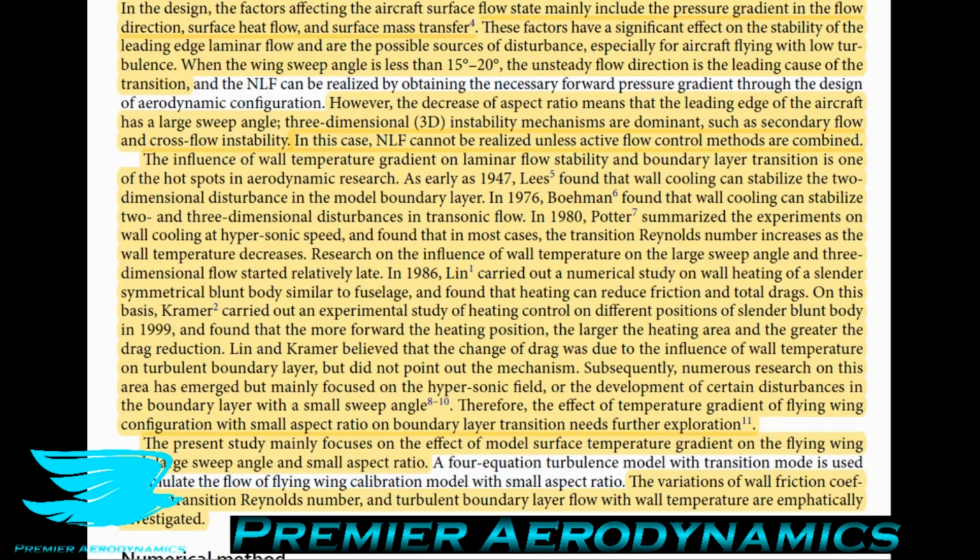which reminds me now, I should probably mention that we were talking about high aspect ratio wings before and why they were very efficient in terms of lift to drag ratio. I did mean to talk about the induced drag there, but I forgot. So let's cover this quickly now. I mentioned that high aspect ratio wings have a much greater lift to drag ratio, which means that they're more efficient than low aspect ratio wings. One of the main reasons for that is the reduction of something called the induced drag.